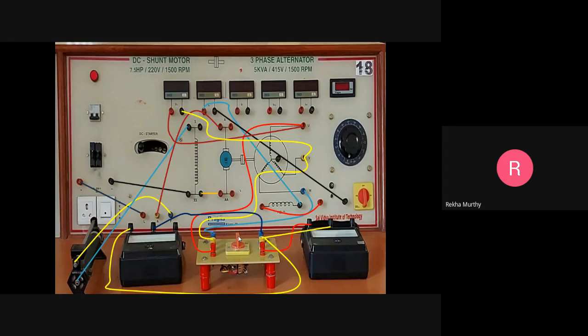Okay. Now we have to switch on the supply. The supply is closed, and the speed of the motor is brought to its rated value by first moving this 3-point starter, and make sure that this rheostat is in cutout position. And by varying this rheostat, we can make the motor run at a rated speed of 1500 RPM. After once it is achieved, what we have to do now?